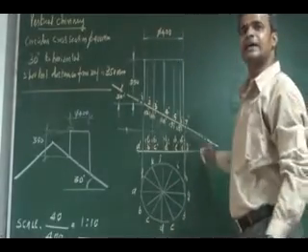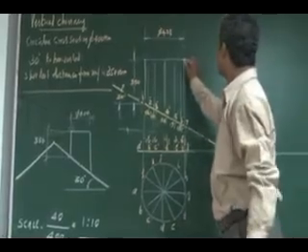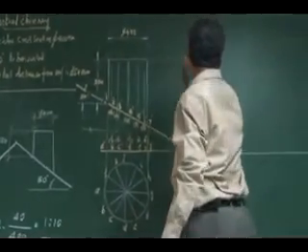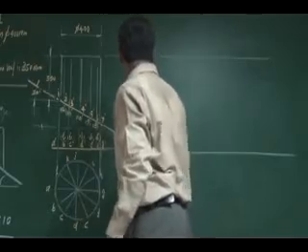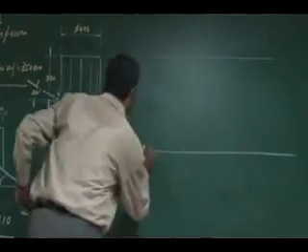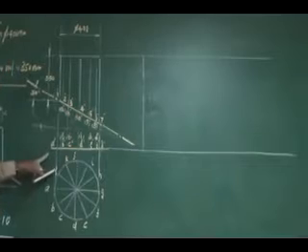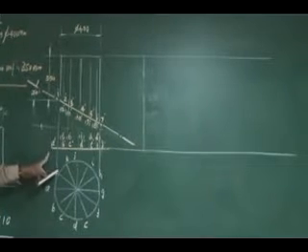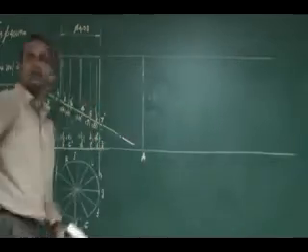So the development of a cylinder, it's very simple. As usual, using parallel line method, I can develop the top base. My development first generator somewhere here. Okay, suppose this is where I am opening here at A, generator A. So this is suppose my generator A, right?